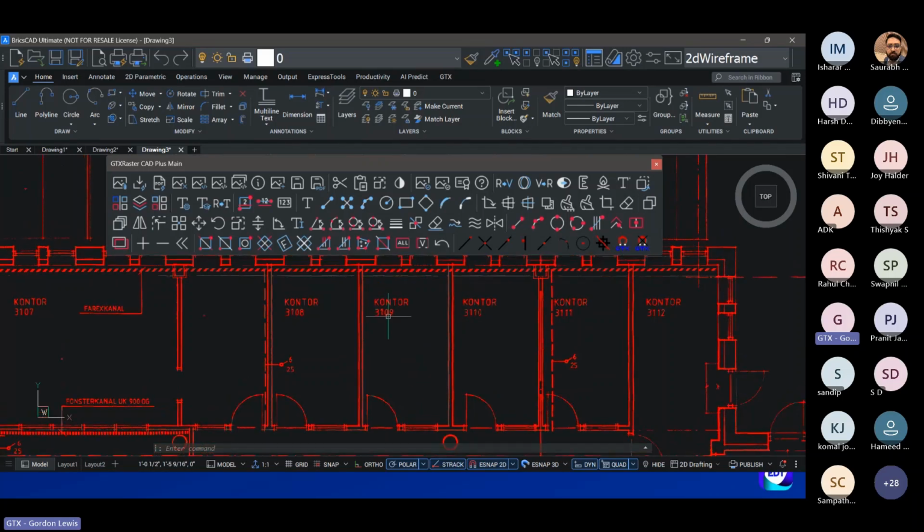Another thing that you might want to do is these 2 rooms, I want to make them into one. So I say erase, I pick a line. So I say, right, I'm going to take this line here, which is a wall. I'm going to take that line there. I can then change it to a window, pick that and pick that. So that's everything I'm going to erase from the drawing.